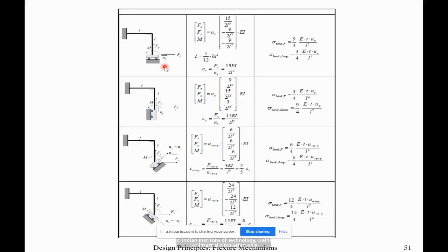But about phi, whether it can rotate? It's clamped, right? It's showing clamped. It's not a dot there. If it's a roller at the end of the flexure and it's a dot, then you may not have a phi there. But if it's shown like this, it means it's clamped, only moving in x direction. So your phi is also 0. Do you agree with that?